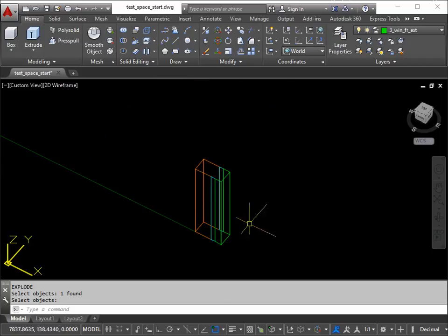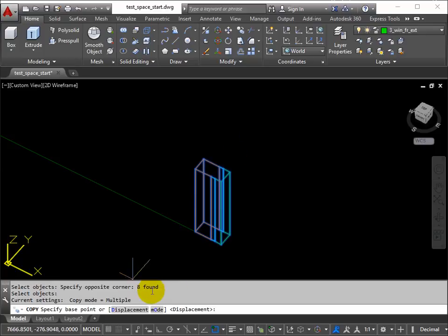Okay, so as I said, we're going to copy this and place it onto the model and then use the section to gauge the heights. So it's copy, so it's CP, return, grab the items and return. Always keep an eye on the number that it finds. Check, you've drawn these 3D faces, you know how many there should be. There's 3 at the back, 2 in the middle, 3 at the front. So that's 3 plus 2 plus 3 is 8.